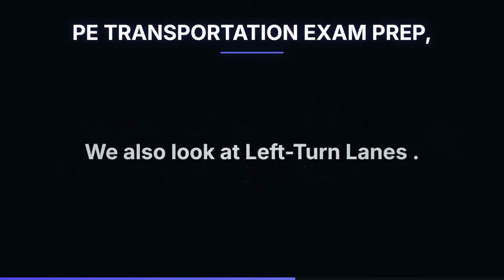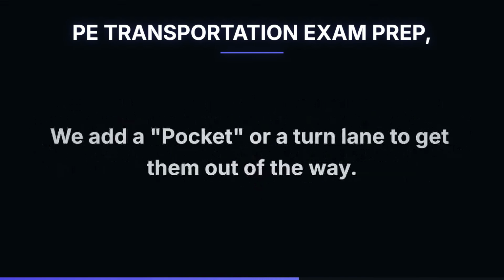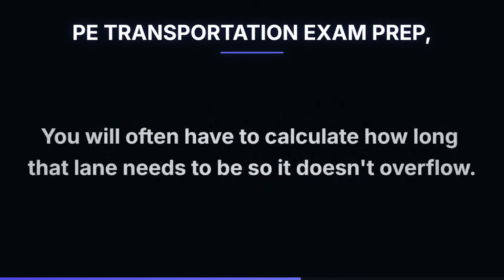We also look at left turn lanes. If you have a lot of people turning left, they block the people going straight. We add a pocket or a turn lane to get them out of the way. You will often have to calculate how long that lane needs to be so it doesn't overflow.